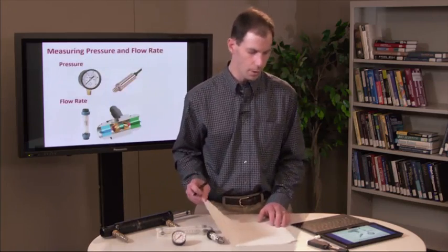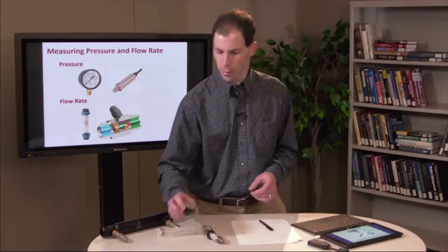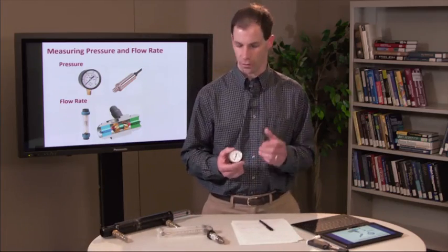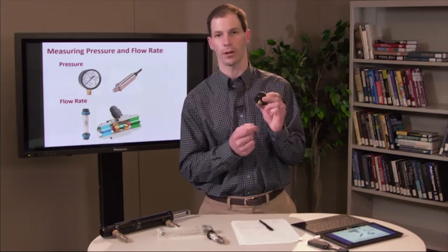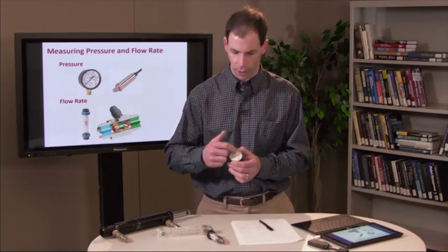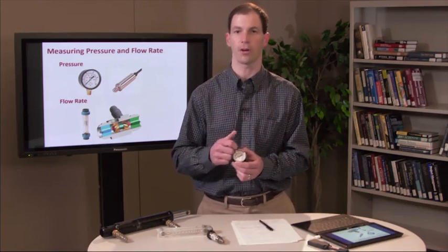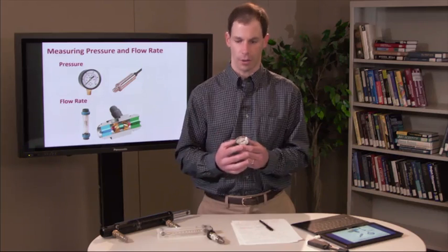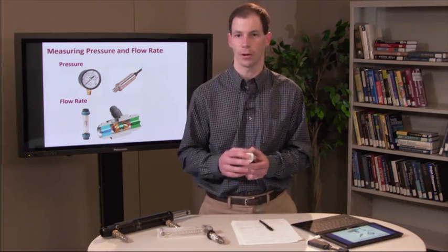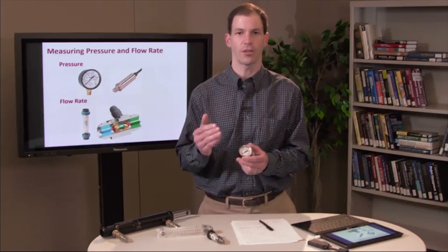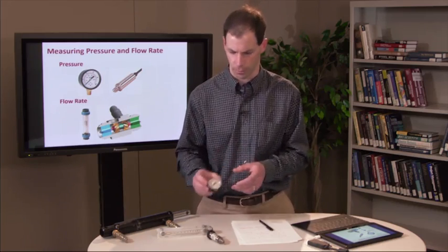So how do we measure pressure and flow? One of the most common devices for measuring pressure is just a pressure gauge. It looks like this, where we've got an input port right here. This is a pipe thread in this case. And then we've got a dial that swings through a pressure in bar and a pressure in PSI. We can use this to quickly glance at the system and say, what's the pressure operating at this point? It also gives you a nice feeling of the time history, because you can watch the needle bouncing around if there are pulsations in the flow.